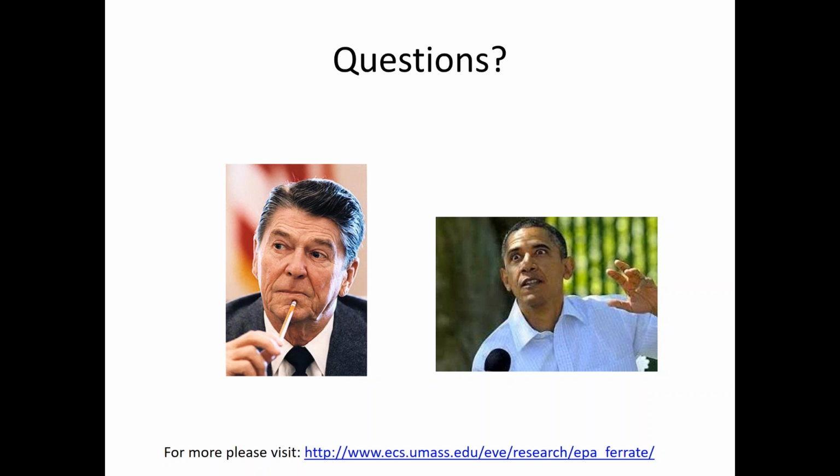All right, that's good. I have a few more questions for you. How stable is the solution, and what is the shelf life? Yeah, so the chemical itself, if you keep it dry, the dry chemical, has a shelf life of, in our experience, a year or more. So it does last a long time, but you do need to make sure that it's kept reasonably dry. In a solution, it will decay, as I showed, and so we're anticipating that with the use of stabilizers, you'll be able to keep it for a day without losing too much of its strength, but you don't want to go any further than that.